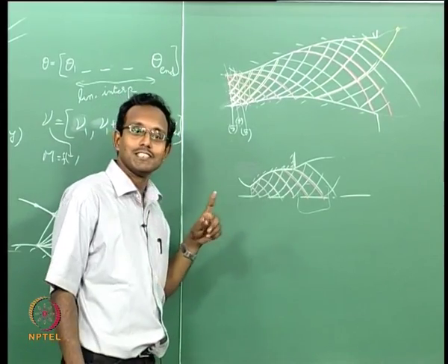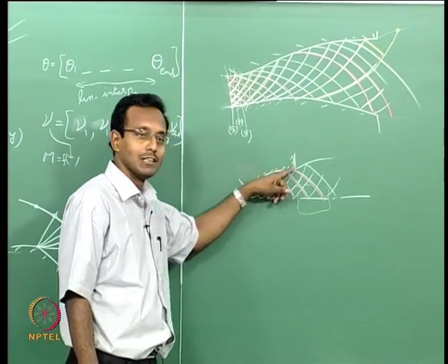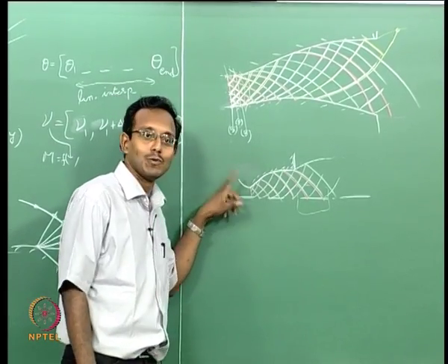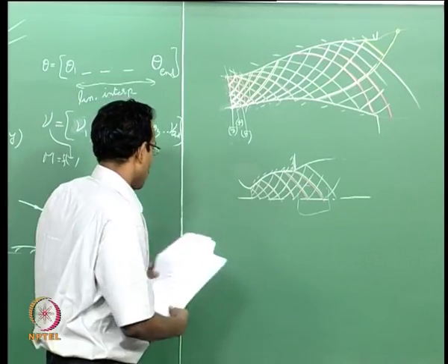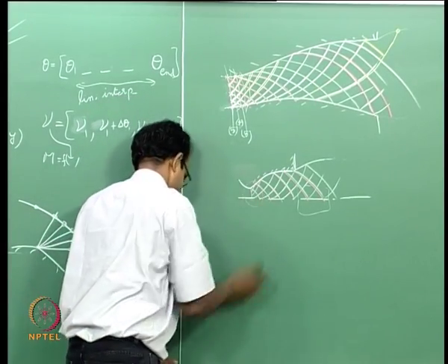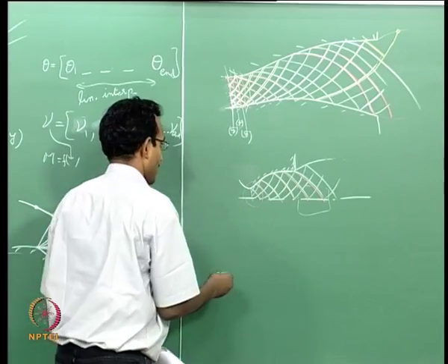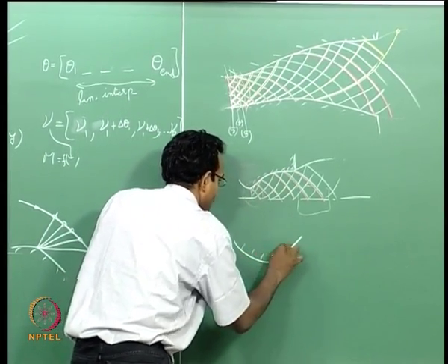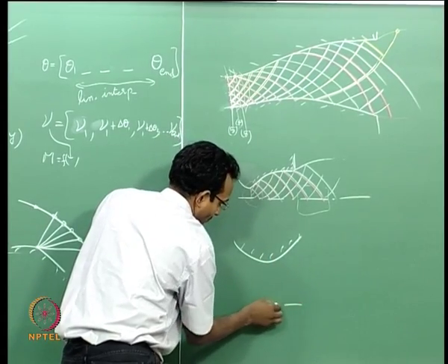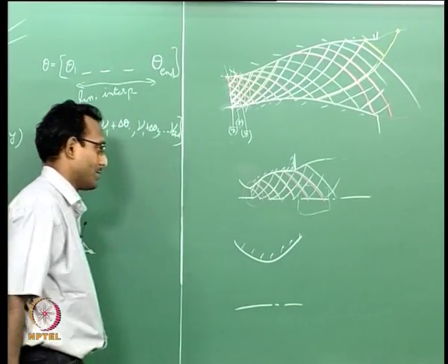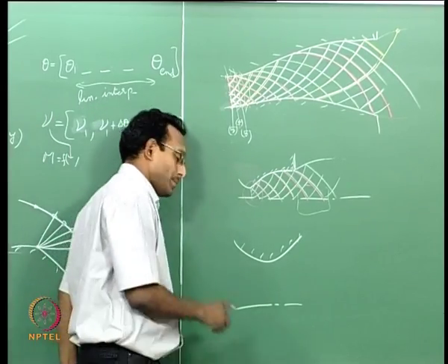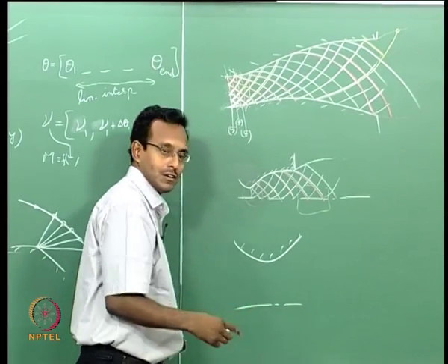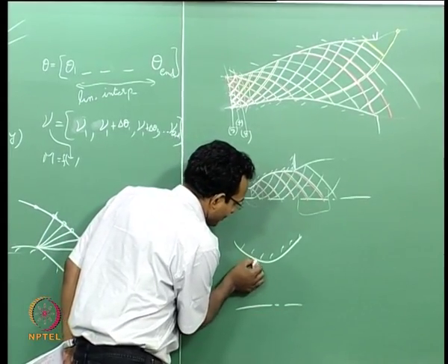That is one such case happens in a nozzle throat. Nozzle throat, we know it is somewhere there M equal to 1. Okay. So if I expand just this region, if I think about just that region, something like this. Now typically if you are looking at the transonic flow around this region, Mach line contours look like this.